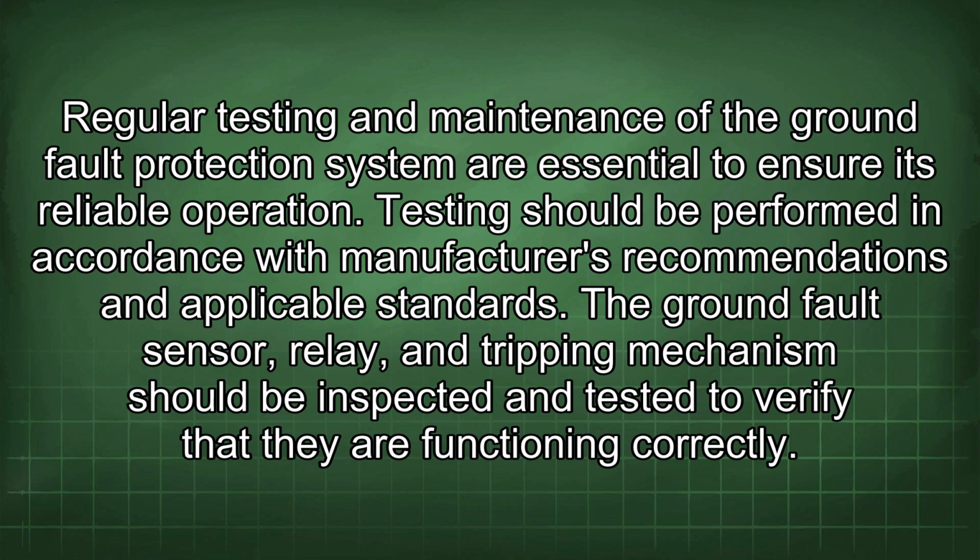Regular testing and maintenance of the ground fault protection system are essential to ensure its reliable operation. Testing should be performed in accordance with manufacturers' recommendations and applicable standards. The ground fault sensor, relay, and tripping mechanism should be inspected and tested to verify that they are functioning correctly.